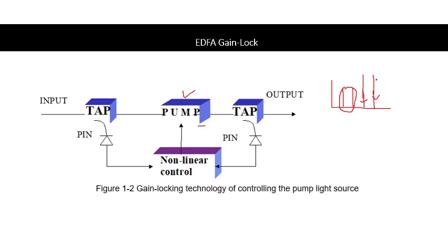So we don't want to do that in a particular WDM system, because it will eventually harm your receiver, or because these overshoot channels are not in control, and they can damage your receiver transponder. And we want the gain to be at a certain level, so that we are controlling the system. So this is a particular control mechanism, also known as clamping.